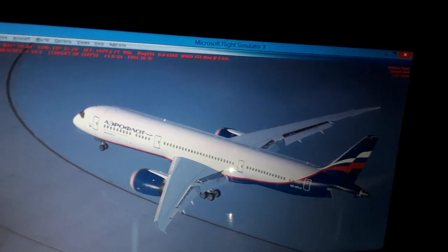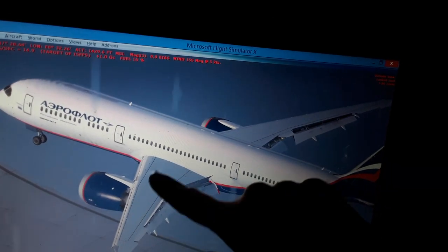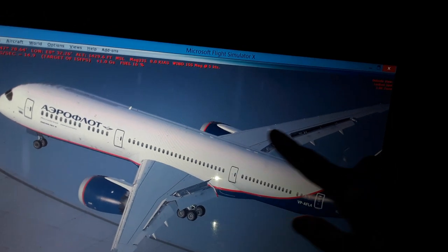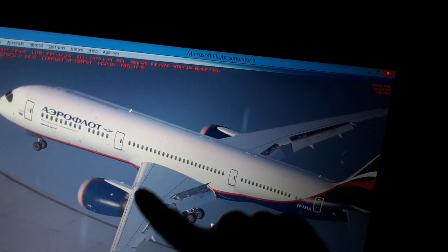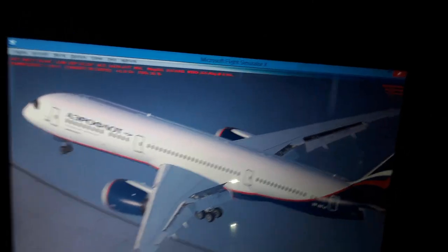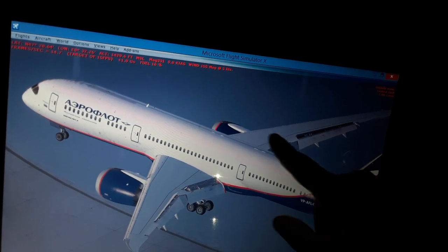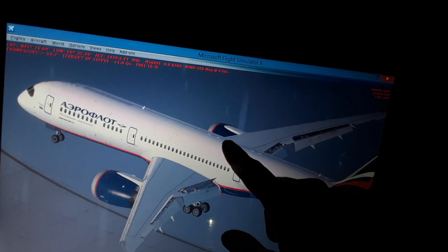We have the thrust, the propulsion from the engines. We have the mean aerodynamic chord position, 23% here. It is the position where maximum aerodynamic lift occurs in the wings, also where the stall will begin. So we need to avoid the stall in flight. The airflow will become detached from the top surface of the wings.